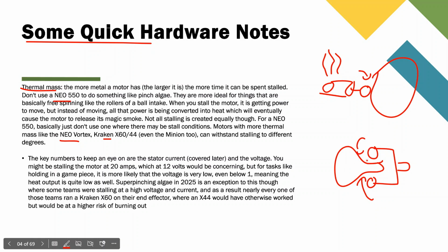It's being pressed against some other things or super pinching it. And so this can cause this one mechanism to take a lot more amps and a lot more voltage than you want it to, because you have to run your drivetrain, your arms, your elevators. You really don't want this one thing to take up all 12 volts of your robot.